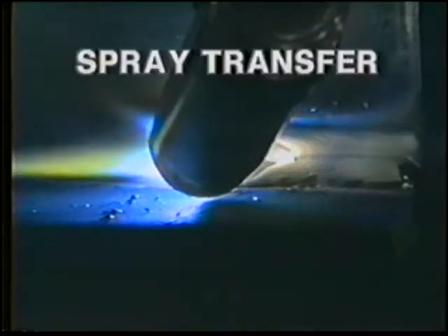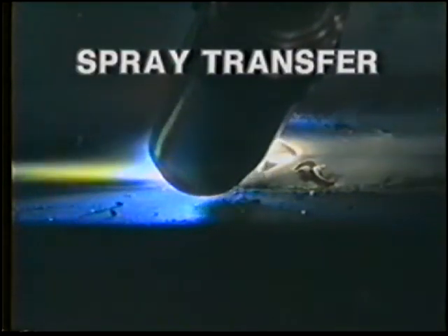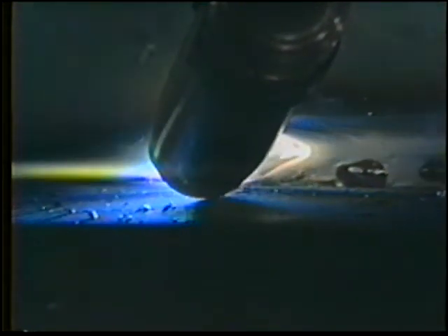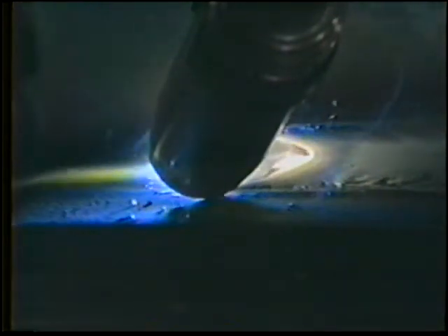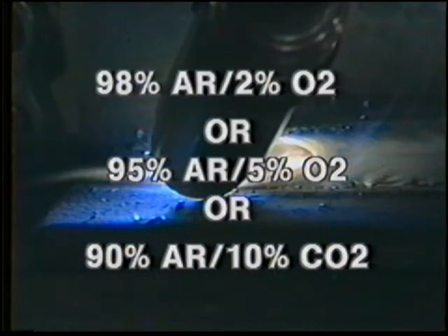Spray transfer is used for metals about an 1/8 inch and thicker in the flat position. The characteristic humming sound is a result of adequate voltage and amperage to pinch the wire off in small droplets. Spray transfer also requires an argon-rich shielding gas. On carbon steel material, up to 5% oxygen or 10% CO2 can be mixed with argon to provide proper puddle wetting action and prevent undercut.